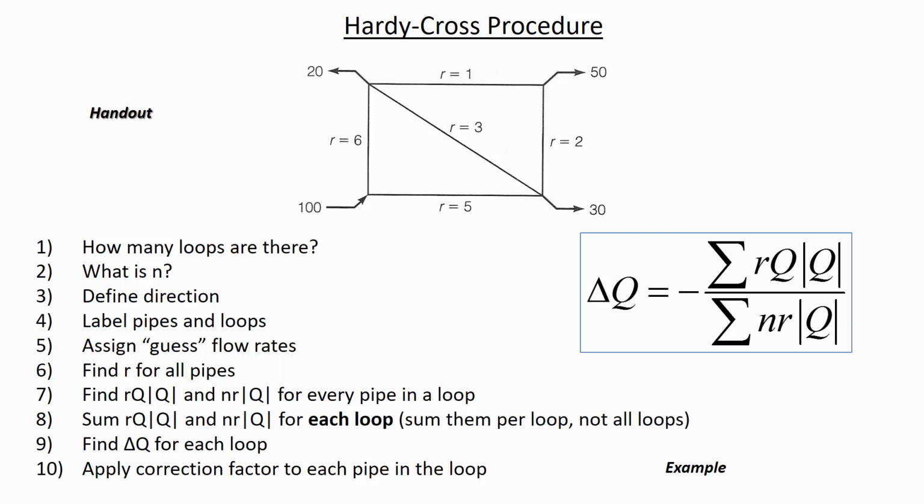If we knew the pressure at one junction, we could calculate the pressures at the rest. But if you increased the flow rate and kept the pipe diameters the same, then the pressures would go down. But you can't have more flow coming out of a network than is going in, unless there's a reservoir somewhere, like a tank up on a hill that's allowing the flow to equalize.